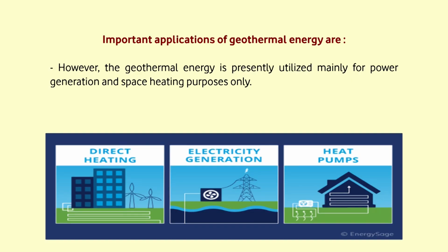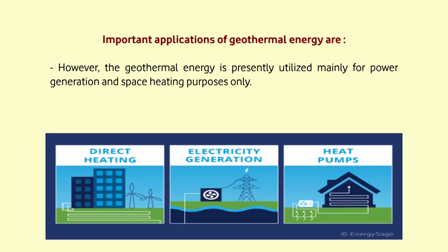Geothermal energy is extracted from the earth through the dry steam technique. Steam from hot water is converted into power using the turbine and generator, then injected back into the earth's surface after cooling. Geothermal heat pumps. Geothermal heat pumps function by using geothermal energy found within 300 meters of the earth's surface, which has a moderate temperature. The GHPs help draw warm air from a building to cool it down during summer. On the contrary, they warm the building in the winter season.